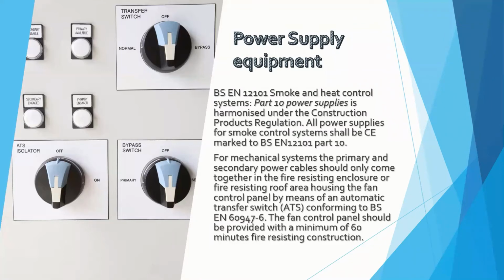Power supply equipment for smoke and heat control relies on sensors and should be CE marked to conform with BS EN 12101 Part 10. Alternative power supplies are required for smoke control systems, and they work together by means of an automatic transfer switch.